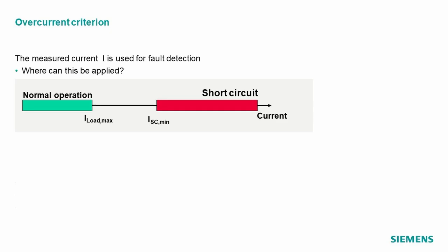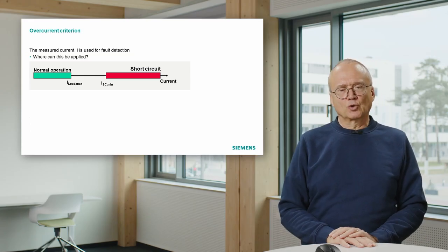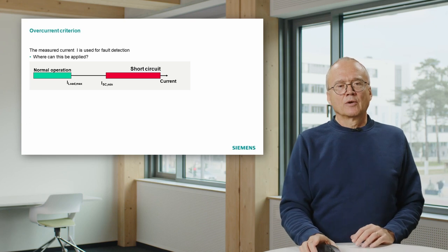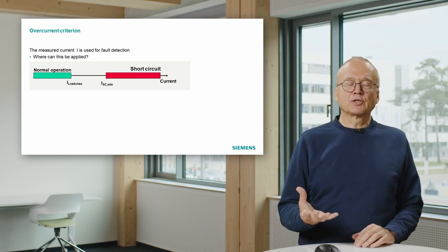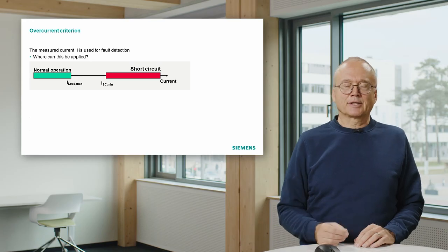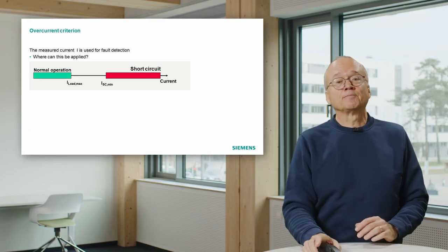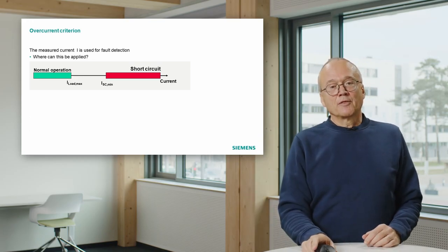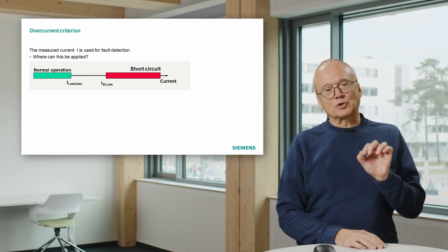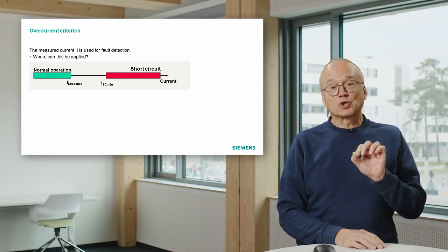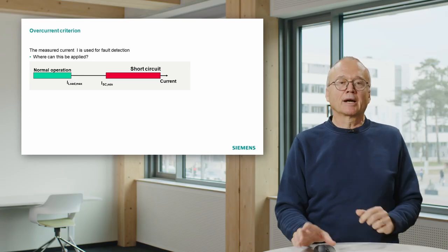Typically, when you engineer your substation, you calculate the maximum short circuit current which may occur. That is always required to dimension the cross-section, for instance, of the cable. That is the maximum current at the right-hand side, but we are, of course, not interested only in short circuits with the maximum current.